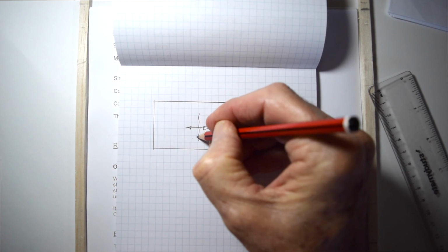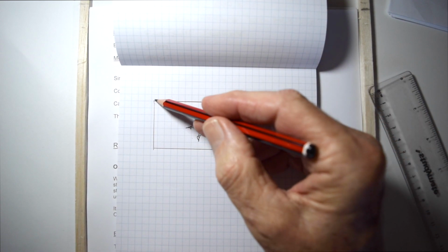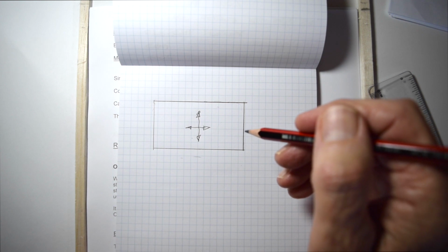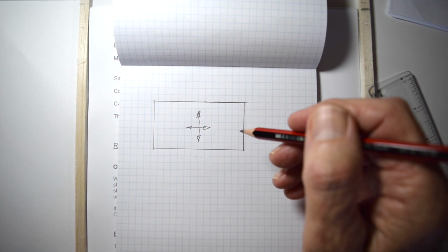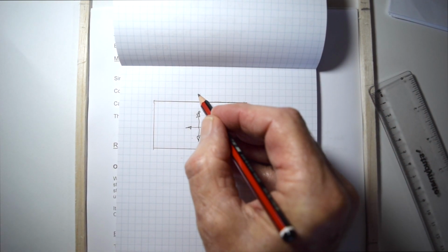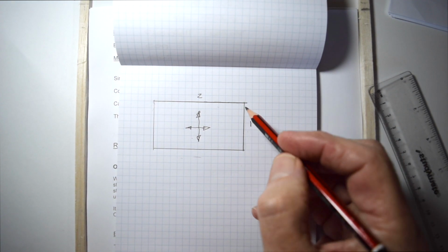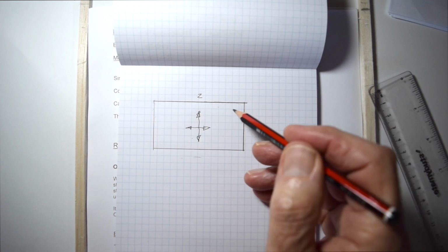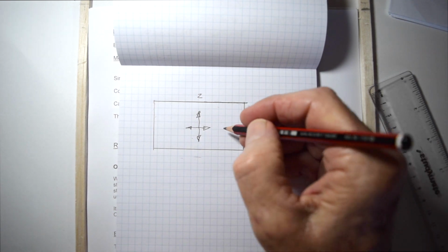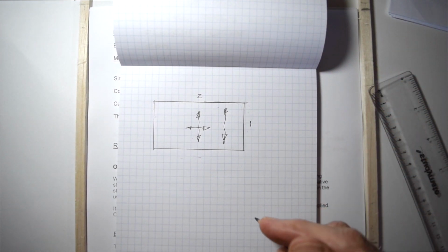and this way. And the bending moment will always be greater in the shorter direction where a slab is supported on four sides. And we'll be doing that in the next session in lecture number 11. But that only holds good for this sort of ratio. If that is two, if there's 2 units, then that's 1 unit. Once this dimension gets more than twice this dimension, then the slab just tends to span one way, like that. And that's what we're looking at today.